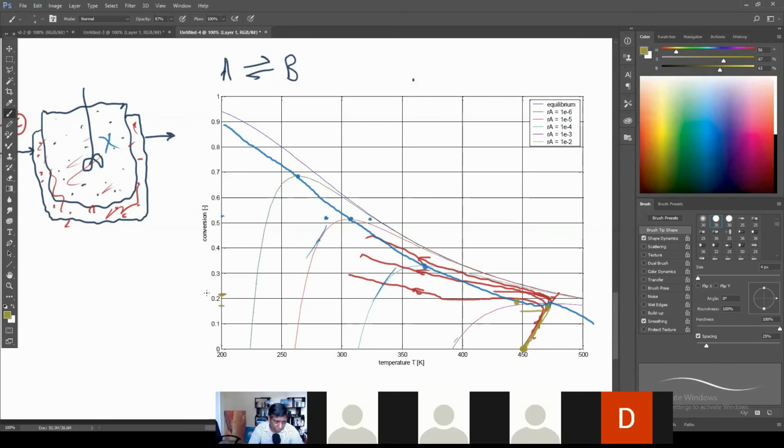So you could go back to your material balance and say, okay, to achieve this conversion, this I can calculate is going to happen over maybe 20 minutes. So within 20 minutes, I need to cool the reactor back by that temperature also. So that tells you what duty is required on your jacket side. And so you can keep doing that.